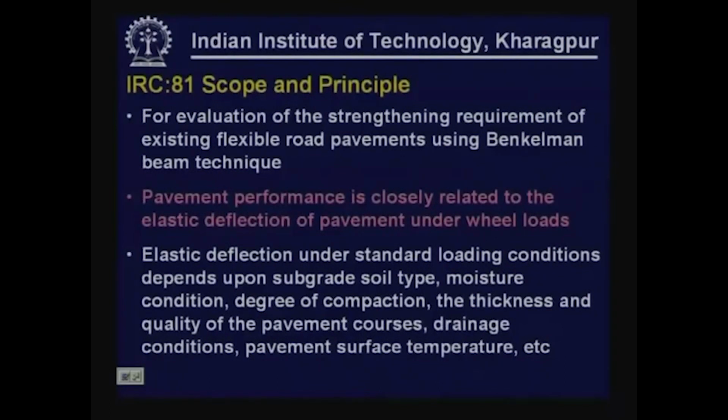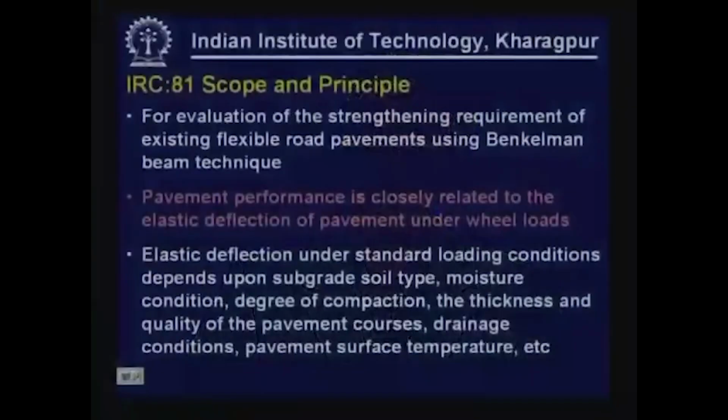Elastic deformation under standard loading conditions depends on various parameters such as the condition of the subgrade, its moisture content, degree of compaction, and the condition of various other layers including granular layers and bituminous layers. It also depends upon various climatic conditions like temperature, provision of drainage, thickness of various layers, and quality of different materials.